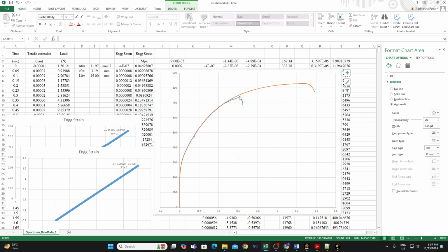Okay, so probably one can say that the initiation of dynamic strain aging is the reason for it to have early failure, that is, to reach the ultimate stress point and have a fracture because of having dynamic strain aging over here. That can be a possible reason, but you can see that the material curve that we have fit with only 15% of strain data, extensometer data, has been valid for a much wider strain range, even beyond the extensometer limit. So that is one positive side, but this difference may be attributed to the initiation of dynamic strain aging, which is a highly rate dependent behavior.